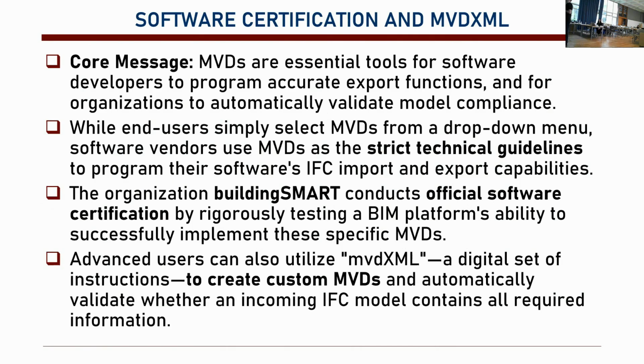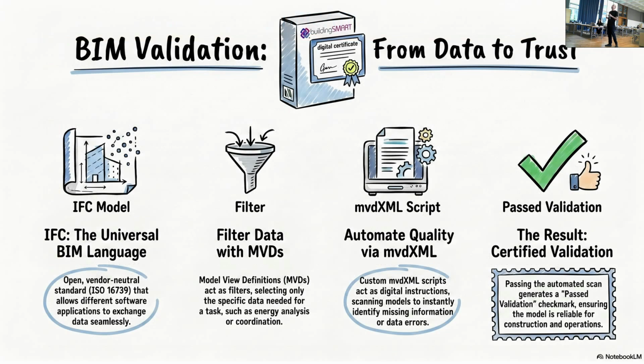And in that regard, we have something called software certification. Again, buildingSMART certifies different software for their capabilities, whether the platform is able to implement MVDs. Advanced users can also use mvdXML to create their custom MVDs and see how the IFC file can be validated for the requirements that are defined within the MVD.